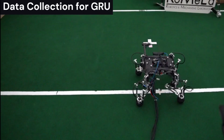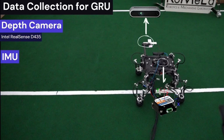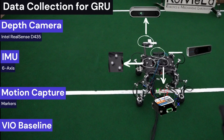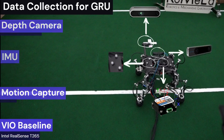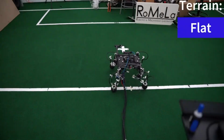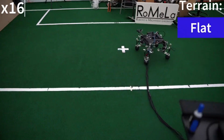We now show the GRU data collection process. We have a depth camera that is angled about 45 degrees to the ground, a 6-axis IMU, a motion capture system to measure the ground truth, and a T265 camera which runs VIO SLAM and is used for our baseline studies. We now show the GRU data collection process, starting with motion on flat terrain.